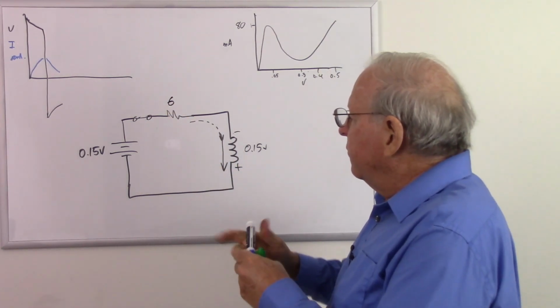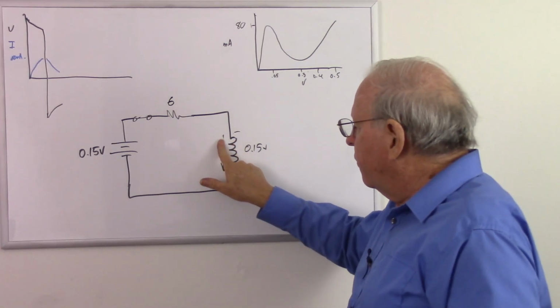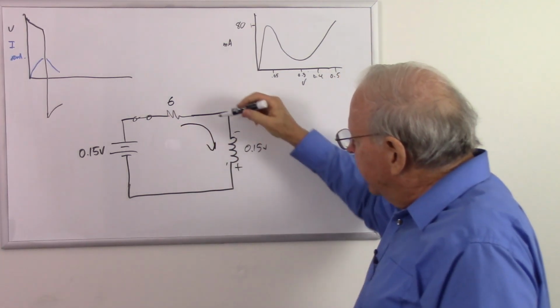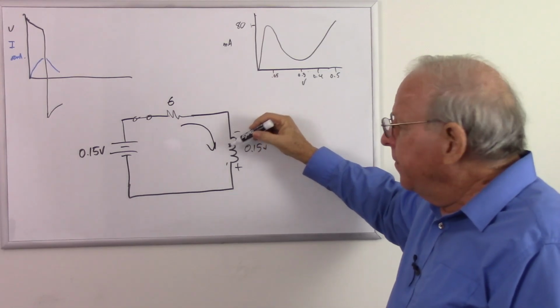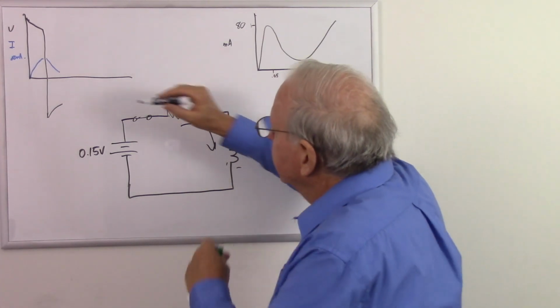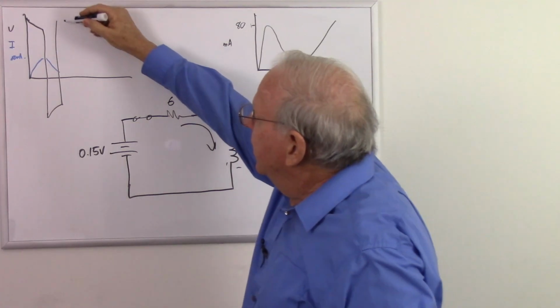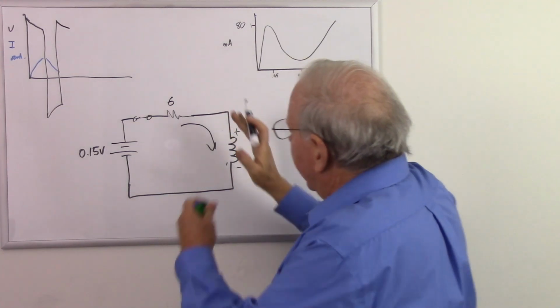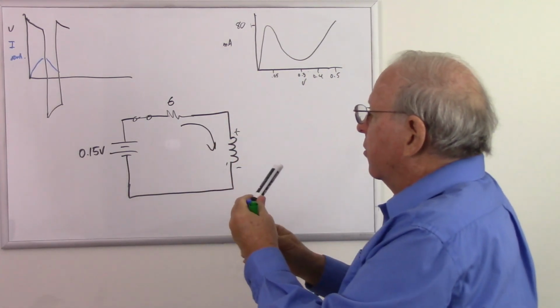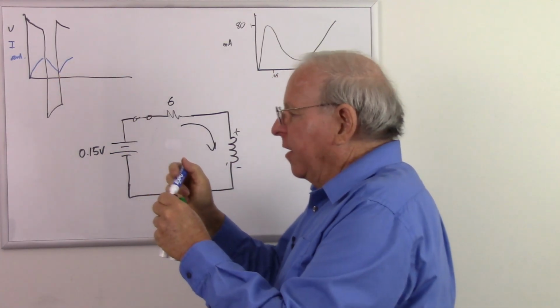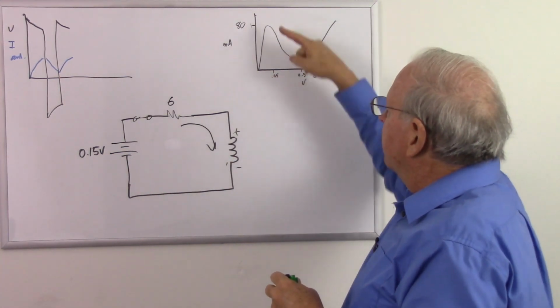So now we've dropped that down to 6 ohms, and like we did before, now our current's going to start pushing back in. What's going to happen? Now our current is pushing into the inductor. So now that voltage is going to reverse polarity. It's going to start going down as that magnetic field slows down. And of course, what's our current going to do? It's going to be increasing. And then when it gets back to 80 milliamps, I guess we're back over here again.